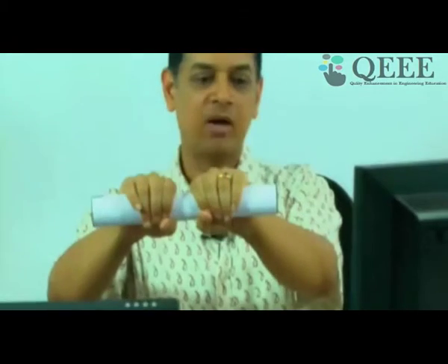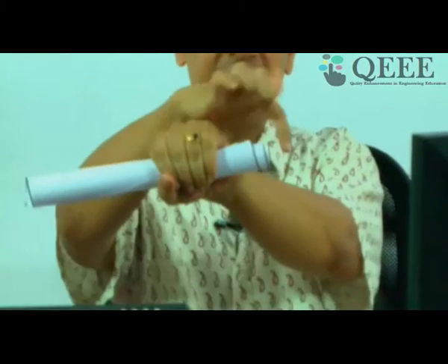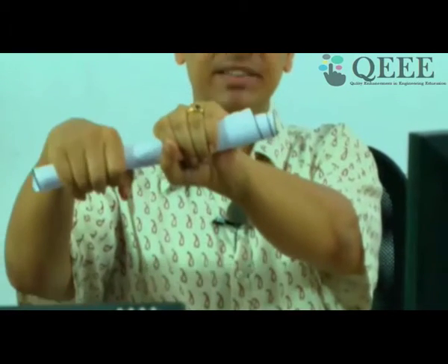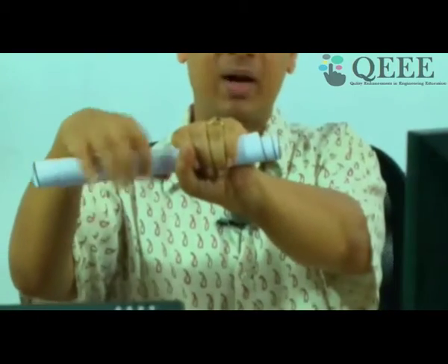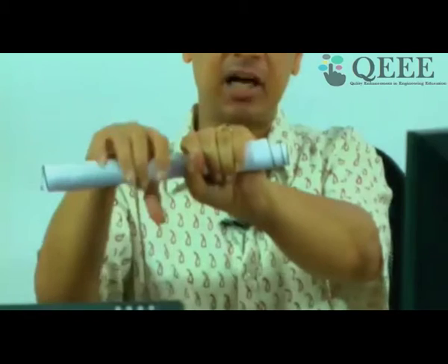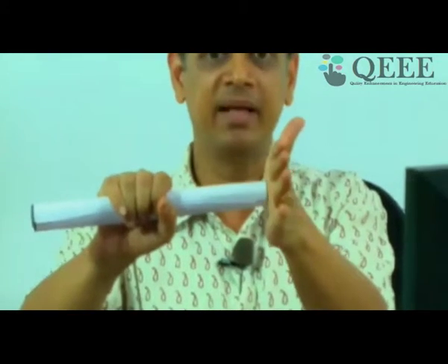Okay, so I want to show it to you by just twisting this sheet of paper. I hope he's zooming on this. So look at the ends. I've just marked them a little bit black. So now I'm just twisting this paper, and you can see that one end goes inside and the other end comes out. Okay, so when I twist this section, this is an open section. I have not glued the paper. So when I twist this, one end is going in and the other end is coming out. So basically we realize that plane sections which are plane, they are not remaining plane after twisting, right? So that is what is called warping.